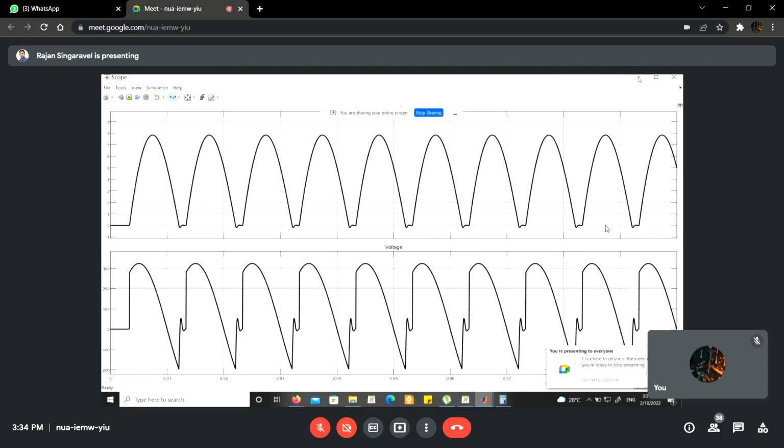And another thing you have to understand, for the same negative voltage across the load terminal, which will bring down the average DC voltage. Right? Don't worry about RMS. If the inductance is increased on the load side, it will decrease the average output voltage across the load terminal.